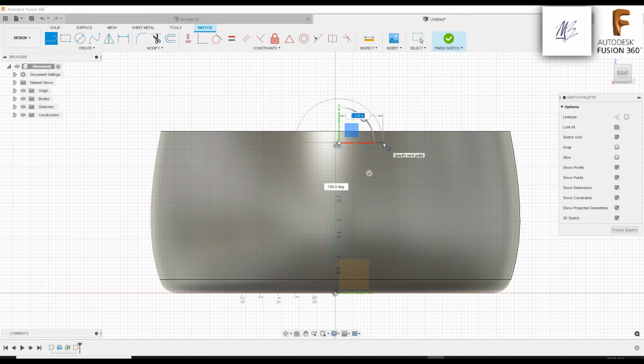Okay. All right, so I got some rough measurements for the handles also, right? So the width of the handle is 3 inches. We want to say 3 1/4 inches. So we're only doing half of the handle, right? Half of the width. So you want to divide 3.25 by 2.